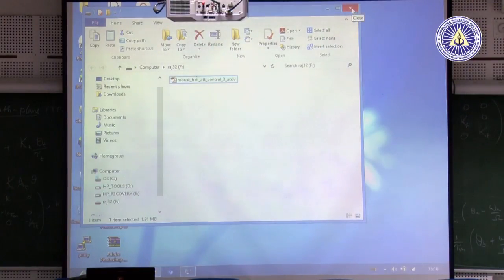Any questions? MT is negligible in comparison to the other one, right? Which one? There are two moments, one because of the spring and one because of the lever arm. Right, so the moment due to the thrust vectoring is negligible when compared to the moment due to the deflection of the rotor. Yeah, that is also there. I forgot to mention that.